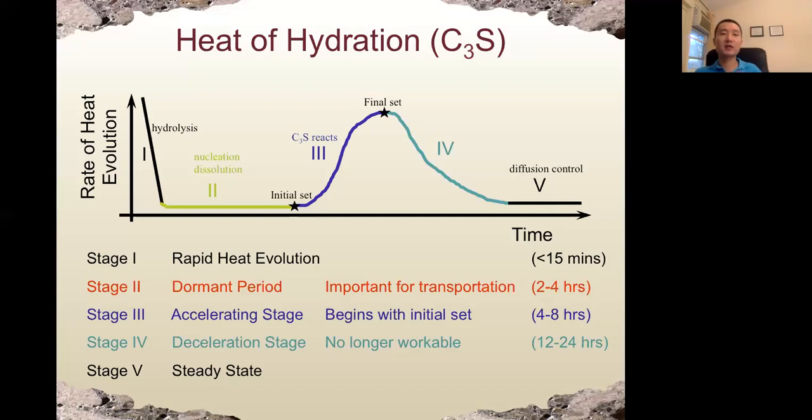This morning, I just uploaded a handout about the hydration process of cement. Please read it after the class. Okay, so pay attention to these slides. You need to understand why we have these 5 different stages and try to understand what the threshold concentration is. Remember, not much hydration product can be produced until the threshold concentration of the ions is achieved. Okay, so this is the important concept.